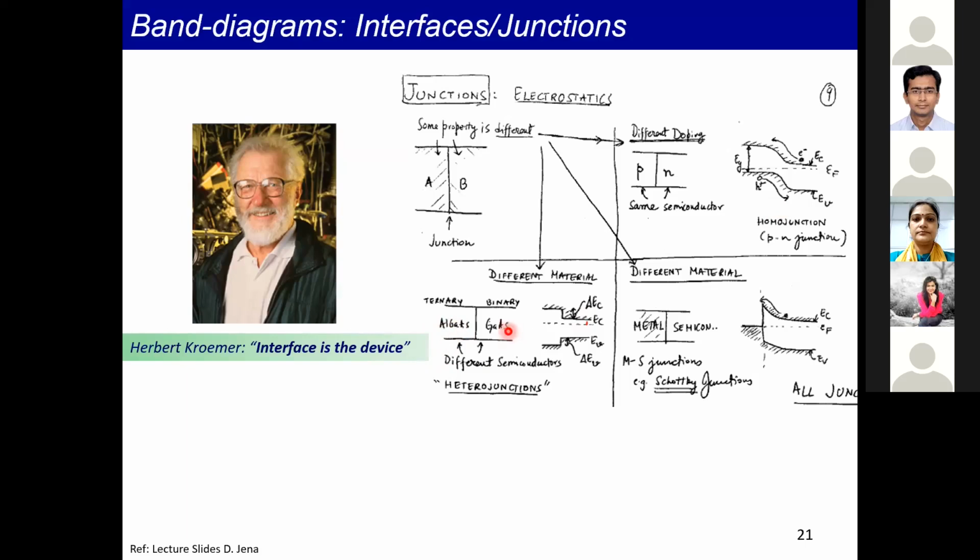Okay. It can be a heterostructure between two different materials. You can have conduction band, valence band offset. So these are used for making high electron mobility transistors. Then it can be two different materials like metal and semiconductors. So you get Schottky diodes, or like what the lady earlier was mentioning, say HBN, graphene, or whatever two materials. So when you put them next to each other, charge transfer can happen between the two. And because of that, barriers get created. These barriers are naturally present when you have two different materials.